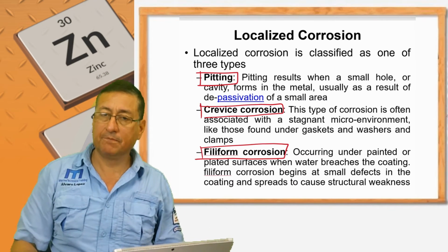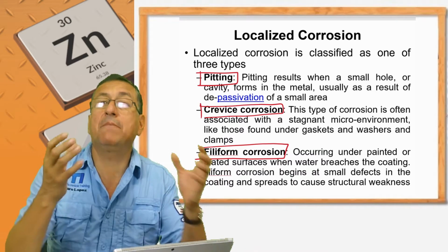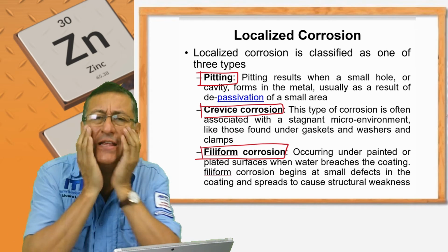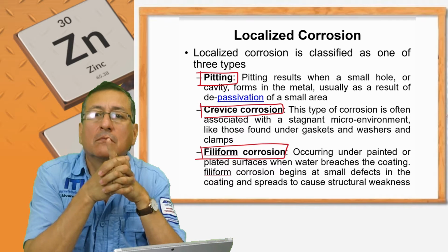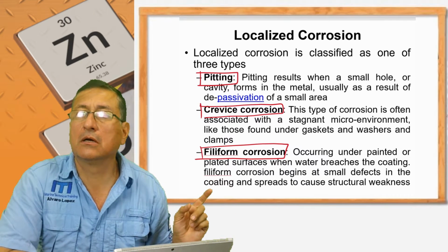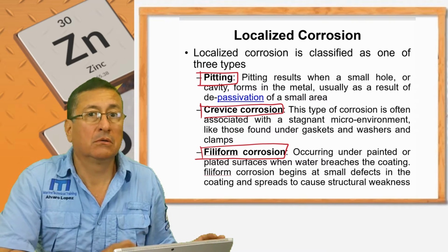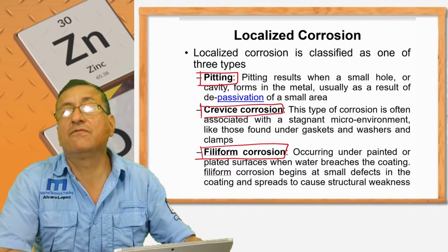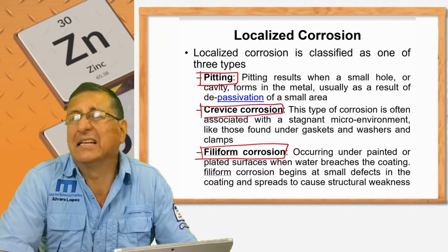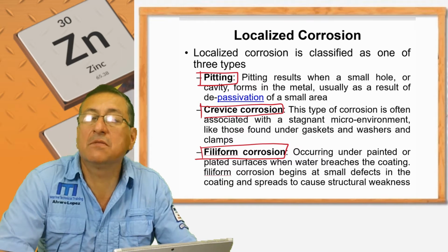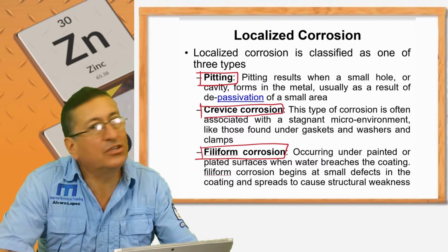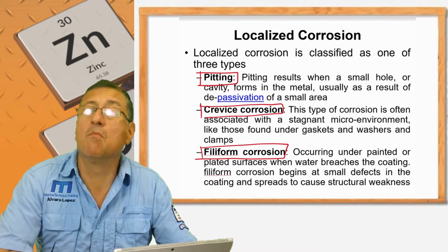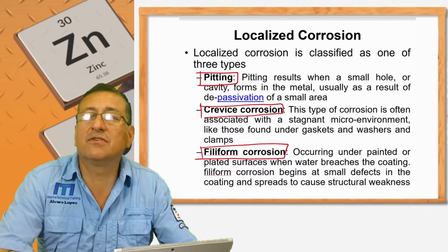And additionally, the metal of the case of the appliance. Why is that refrigerator destroyed in my boat? Excuse me, is that appliance a residential appliance? Yes. I think so. The case of that equipment is steel, plain steel, turned plate, regular steel. This is not good for a marine environment. Yes, marine appliances are more expensive. It's because of the quality of the materials.